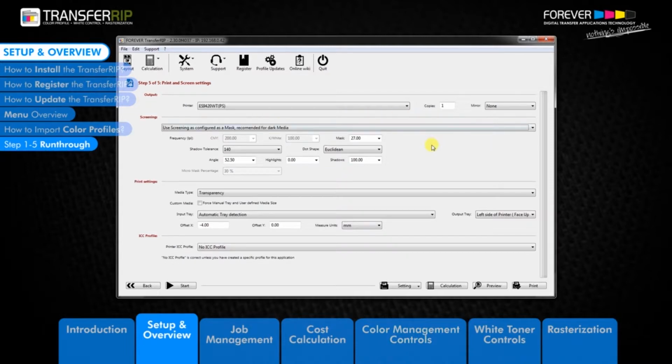The full color areas do not have good washability because these images work against the high water pressure. High water pressure is something we cannot prevent. Rasterized images have lots of holes across the whole design. As they are washed, the images work with the high water pressure rather than against it, by allowing this water to pass through the garment. This prevents images from being destroyed and therefore increases the washability of the image.